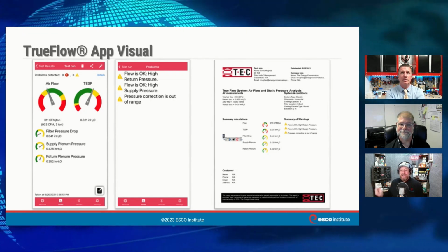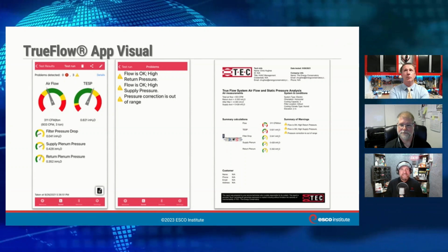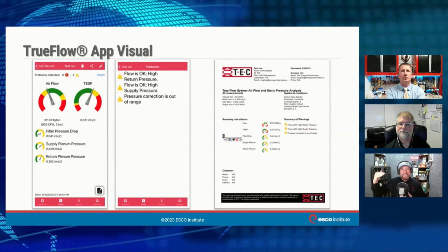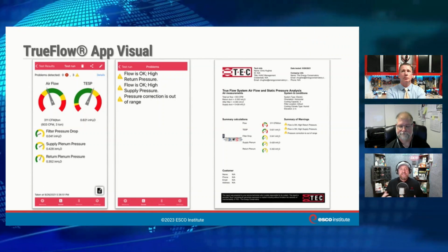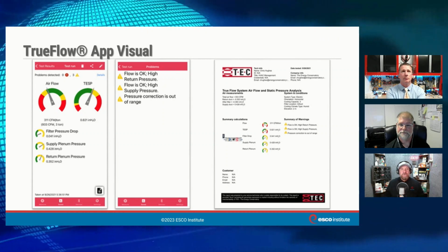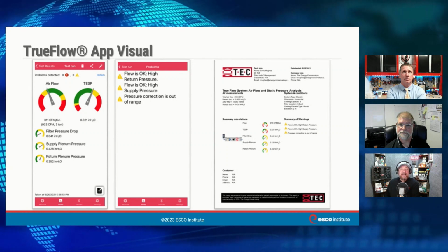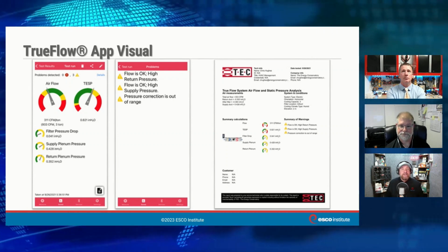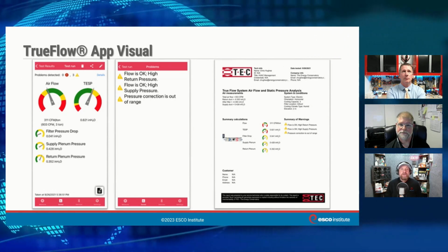So it's got so many different options. One is it just will give you a CFM number, which is super easy and simple to do. But if you put a few more probes in there in different places, it's able to then evaluate where your restriction is or where your most likely problem is. So now by putting it in this red and green, it's telling you, hey, you most likely have an issue in that evaporator coil. So now let's spend the time investigating that, or maybe across your heat exchanger so you can start looking at secondary, or your return is too small. So we got to solve that problem before we go anywhere else.